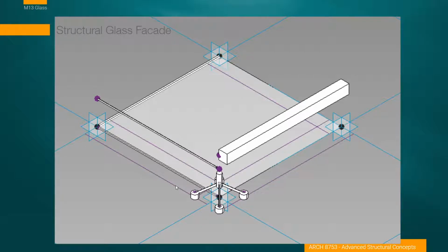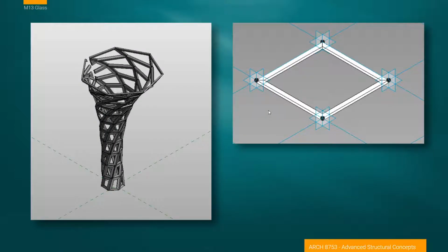This should be very familiar now. We have a 4-point adaptive system, as we might have used in a space frame. We're adding elements in, and then populating a glass curtain wall, a relatively easy system. I also ask you to do a tornado, a structural column system, just to get an idea of applying the ideas we've used to other surfaces that are relatively popular today.